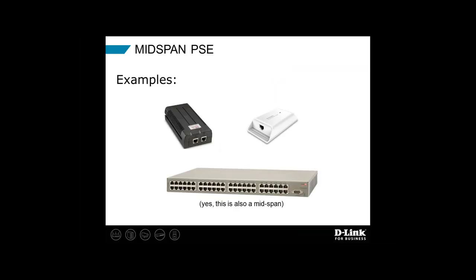Here's a couple examples of MIDSPAN PSEs. The two on the top are single port PSEs and MIDSPANs, and yes, even the device on the bottom, although that looks like a PoE switch, it's not. That's actually a 24 port MIDSPAN PSE. A MIDSPAN typically has 2 ports, an in and an out. So the in is the Ethernet coming in, and the out is the Ethernet coming out with the PoE power also on the cable. A lot of times MIDSPANs are referred to as PoE injectors.